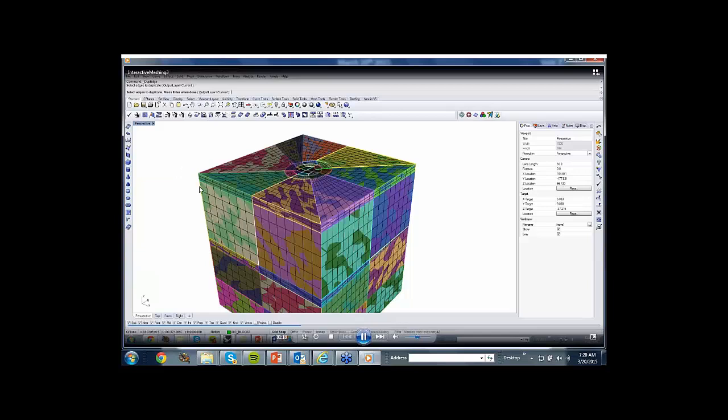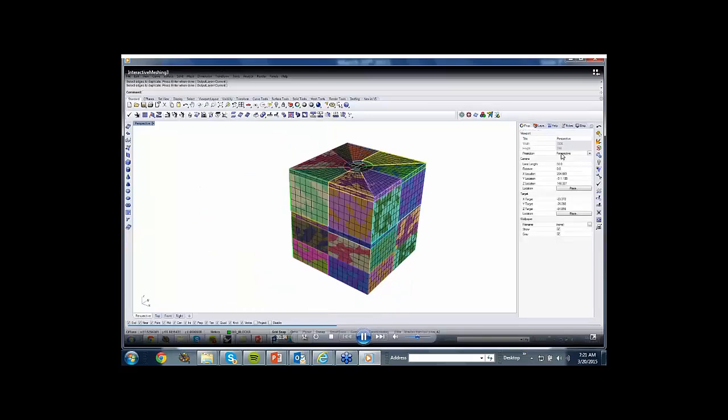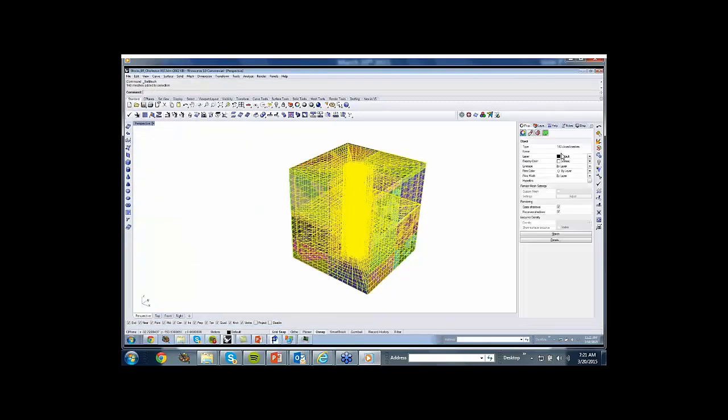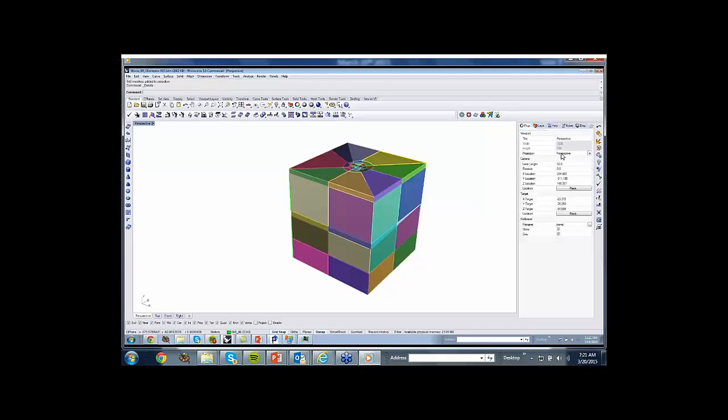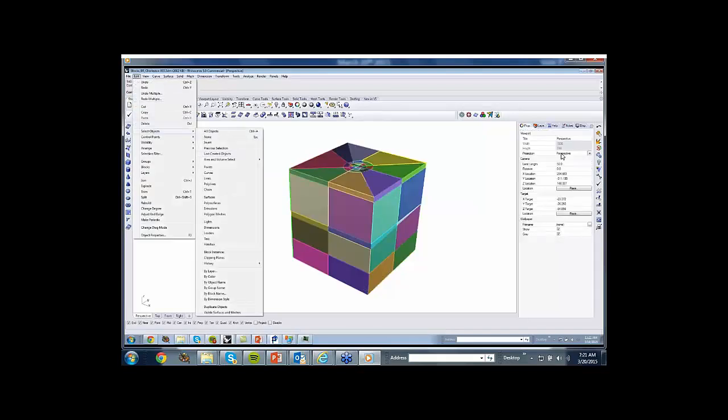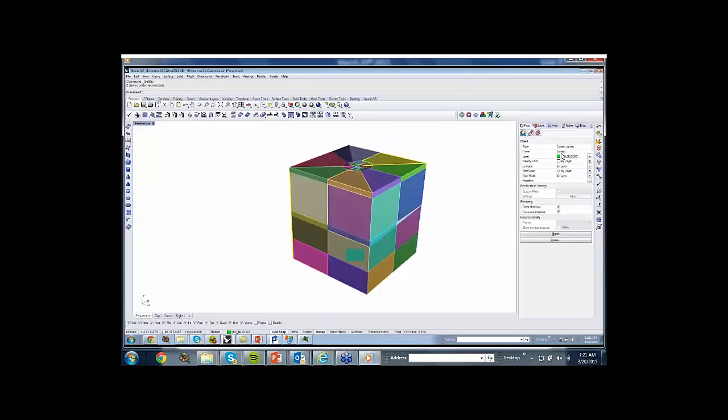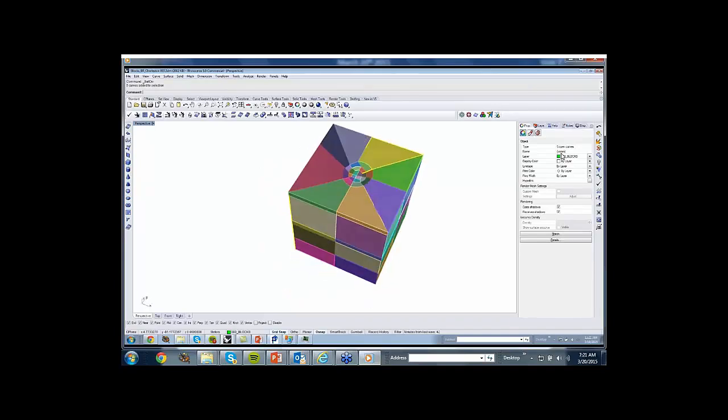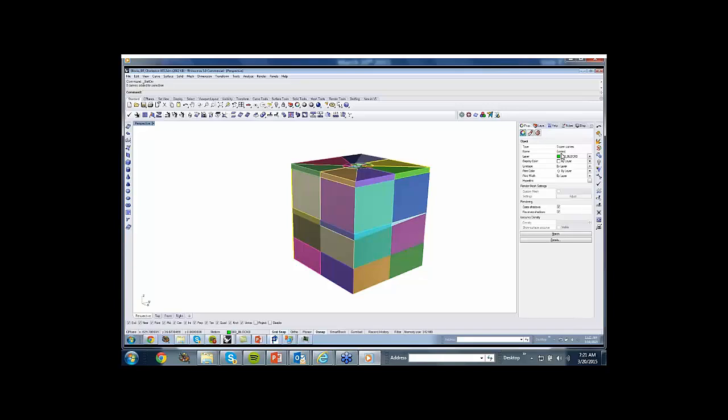Here again, I selected this edge, and then another edge below it, and then another edge below it. I am selecting all these edges at the same time, and collectively on the right side in the name section, I put 10, which indicates that I want these edges to be discretized with 10 elements. So I can select the entire thing. It would be nice to remove the mesh, select the entire collection of solids, but also the curves that now bear an information, which is the edge resolution.